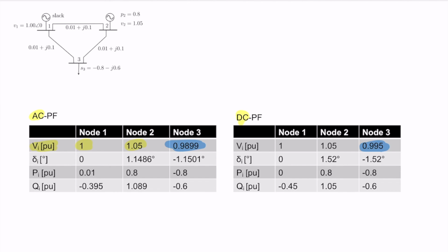So we can have a very fast initial guess of what is going on in the system. And as you remember, linear systems of equations have a very nice property if we check the rank of the matrix which forms this linear set of equations. This is why this linear approach makes a very interesting approximation for the power flow problem.